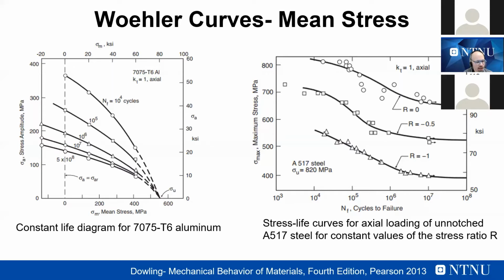When you have an additive manufacturing component, usually we have intrinsic pores or intrinsic defects due to the process that are sometimes close to the free surface of the components. And these defects can be affected by a mean stress that can be different from 0 and greater than 0. And so we need to be able to take into account this effect in the fatigue design.